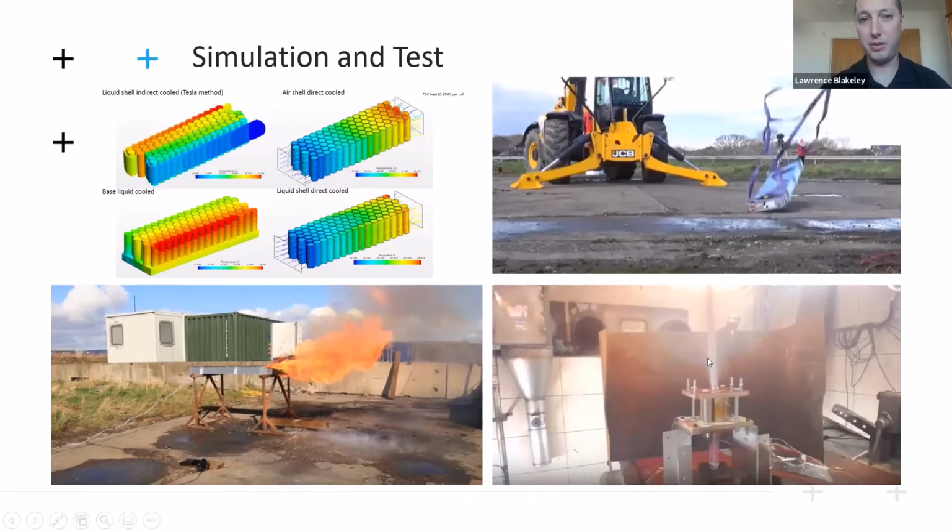And here in the bottom right, this is called an outgas event, which normally is a signature for there being a thermal runaway. So these are some of the elements that we have to model and then have to test to prove out our models.